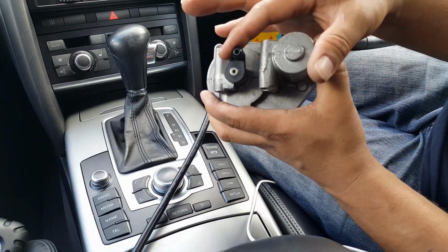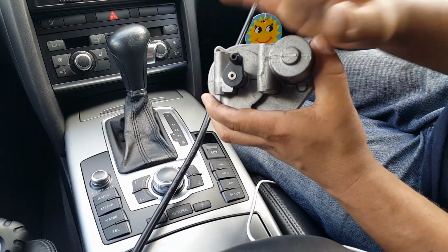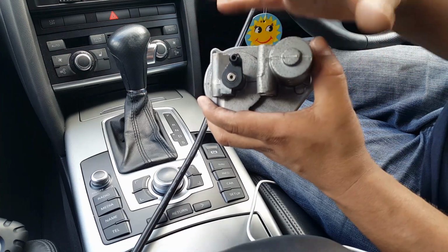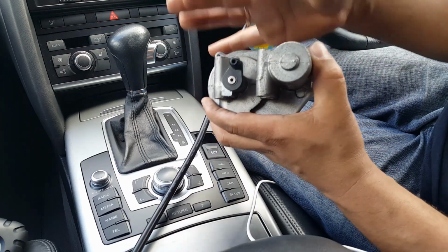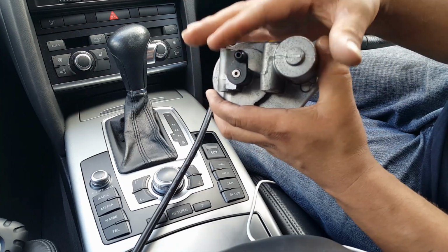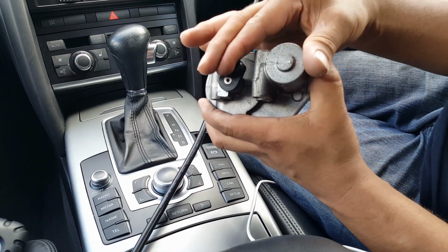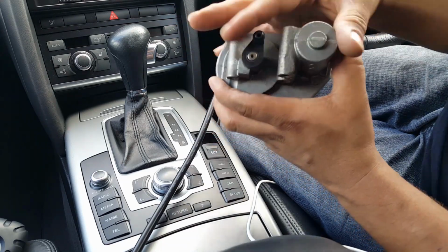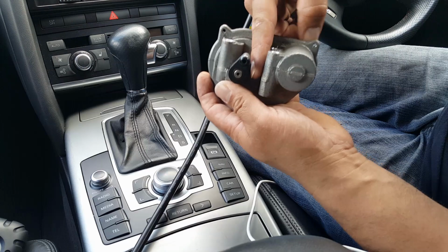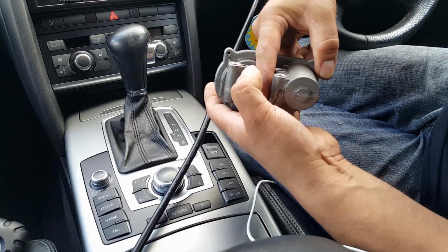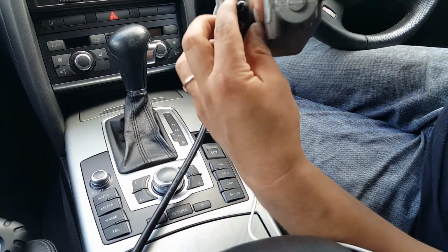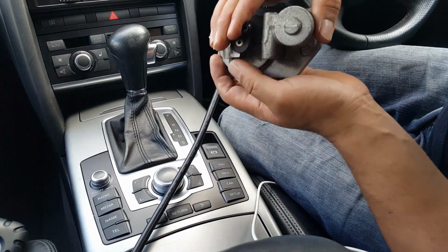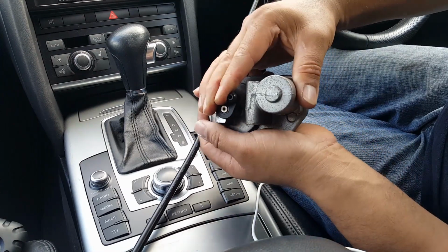And after this moment, you can move it by hand, which you shouldn't be able to, because the ECU should keep that position. But because it deactivates this, you are then able to move it. That's how I know it's not utilizing this anymore, and it activates the fault. So what I've done is, when this is in place, I put a screwdriver under there to stop this before. So when this moves that way, it hits the screwdriver, and obviously stops and comes back straight away.